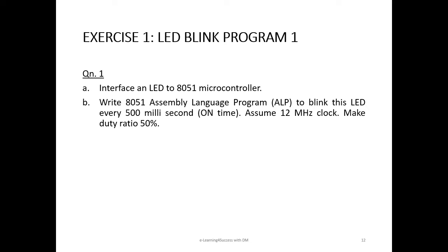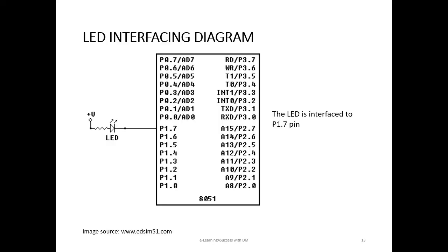Let us discuss the significance of delay in this particular exercise. You might have studied about persistence of vision in your school. In practice, a 500 millisecond time delay is far more than sufficient in between the blinks for the human eye to detect it. This figure shows how the LED is interfaced to the 8051 microcontroller P1.7 pin. You may notice that for this connection, making the P1.7 pin low will turn on this LED.